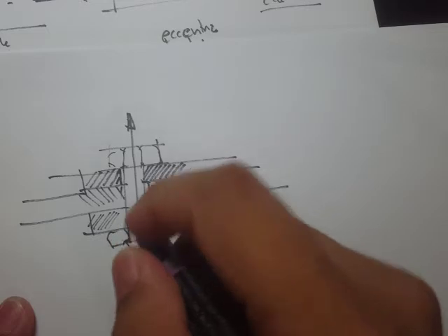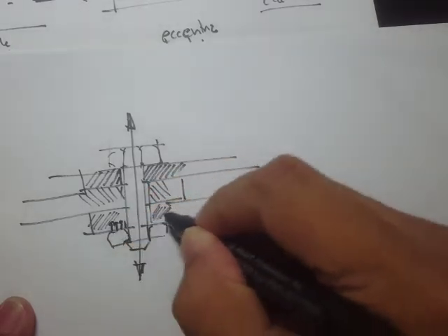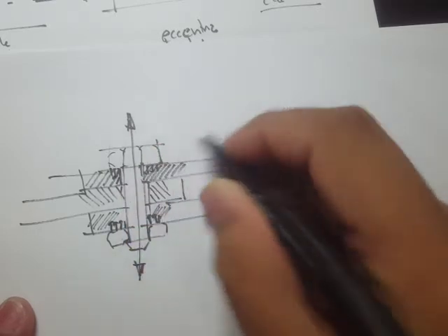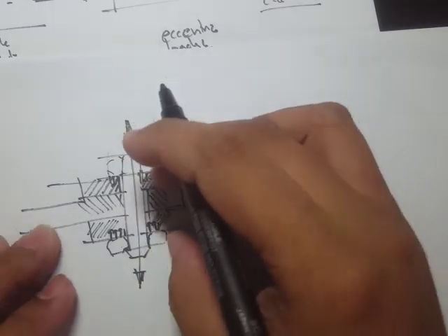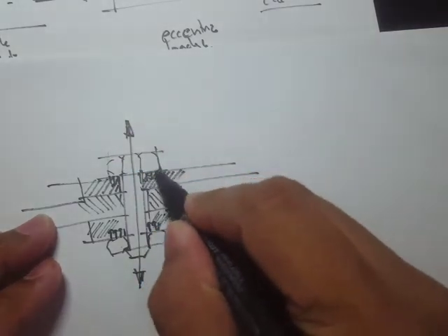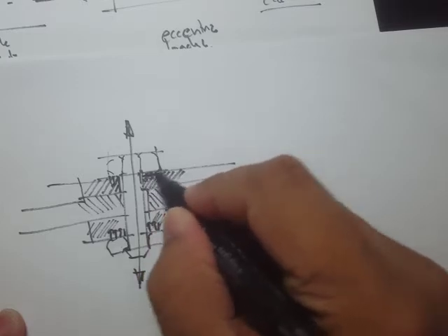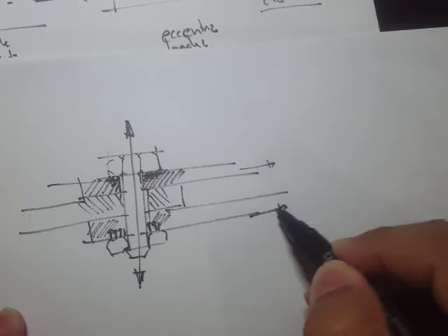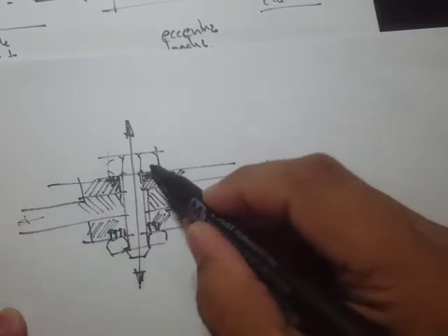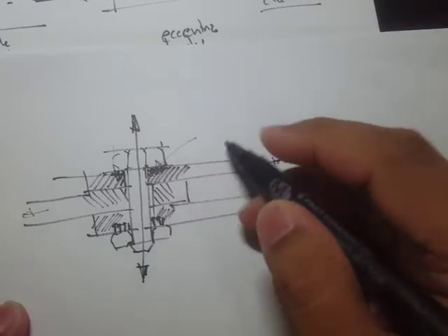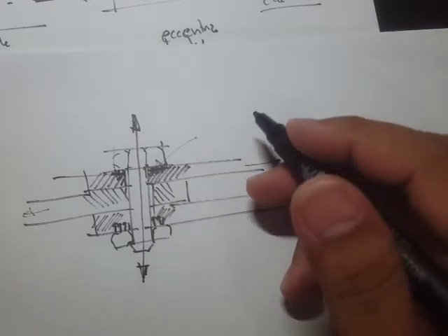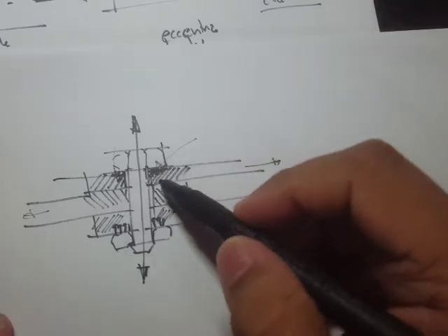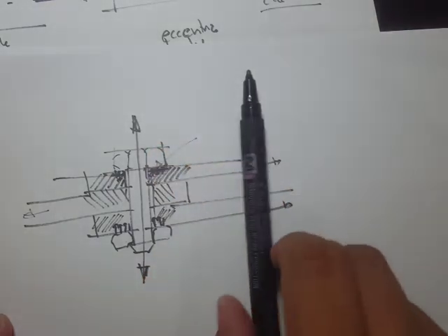So if you're tightening it, you're inducing forces here. So you have forces, and these members are transferring the forces by the friction here. Unless the external force overcomes the static friction in the surface, that's the time that it will start to move, or displace, and probably it will become like a bearing type of connection.